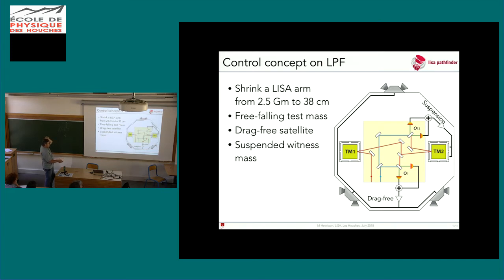And here you see also how the drag-free works. So you see two measurements here interferometrically, and I'll talk about these in a bit more detail. The first one is to measure how the satellite is moving with respect to the test mass. That's identical to what we do on LISA. And then I control the spacecraft by firing these little thrusters to make sure the test mass doesn't hit the wall. The second one is made by measuring the relative position with respect to the first test mass and controlling that to be fixed. Okay, so I have this sort of witness test mass, and because I know what force I've applied on the test mass, I use that in my inference of the differential force that's acting on the two, and we'll see that a bit later on.